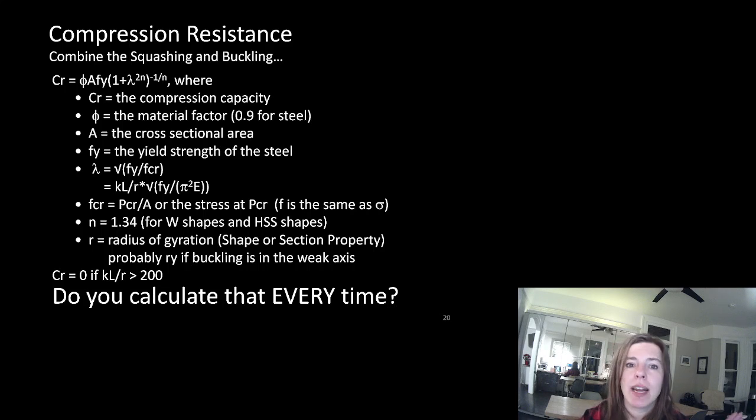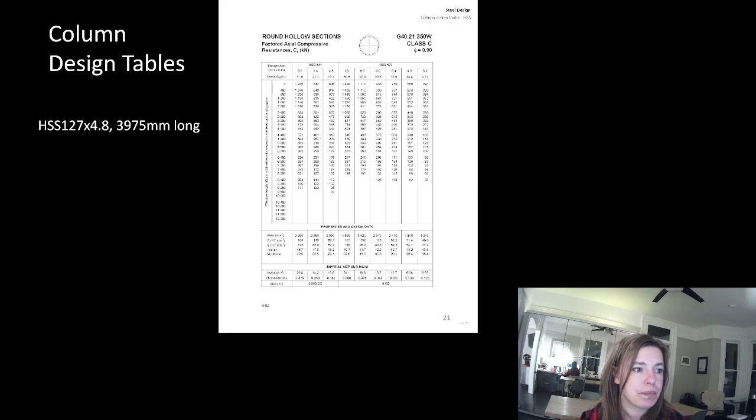They finally just got rid of all of those elements recently. So 350 MPa is now what we would spec on drawings. In the 70s, it was a different strength of steel. So we've gotten better at making our steel. E has stayed the same, but our yield strength has increased.